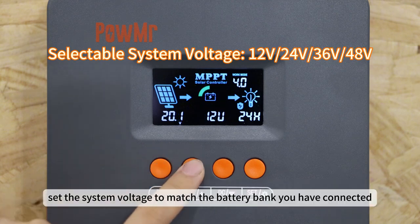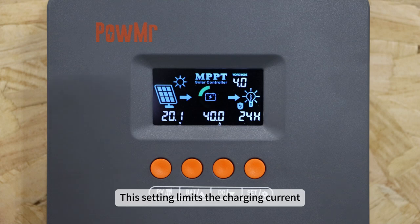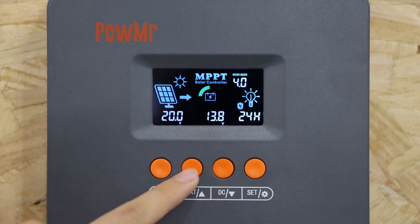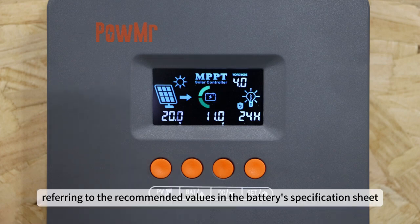First, set the system voltage to match the battery bank you have connected. Next, configure the maximum charging current. This setting limits the charging current to ensure it matches the connected battery and prevent potential damage from excessive current. The configurable range is 2 to 60 amperes. Then set the boost charging voltage, float charging voltage, under voltage recovery voltage, and under voltage cutoff voltage, referring to the recommended value in the battery specification sheet.